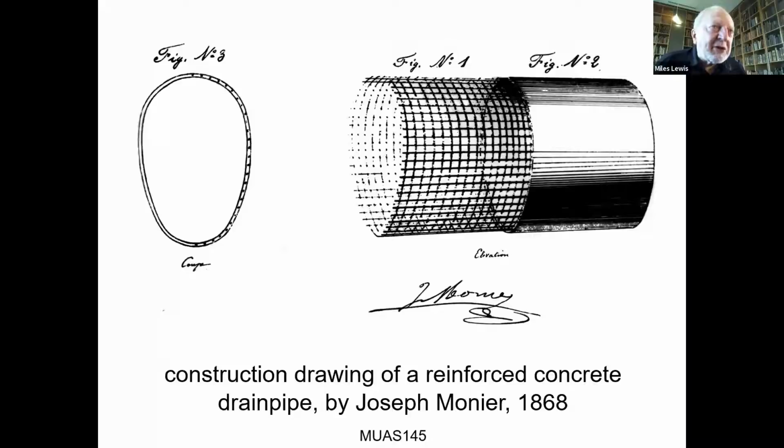The other question I would ask you is, why would you shape a drain pipe in this oval shape rather than circular, or has it just been distorted during the casting? Similar to an egg form, which is meant to be the strongest naturally occurring form, isn't it? Well, it's an egg form, it's an ovoid form, certainly, but what's the benefit of it? You say it's natural, but not as good structurally. A circular is the best shape for resisting compression in a shell like this.